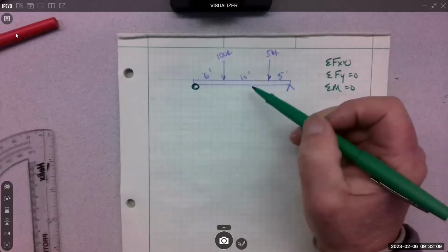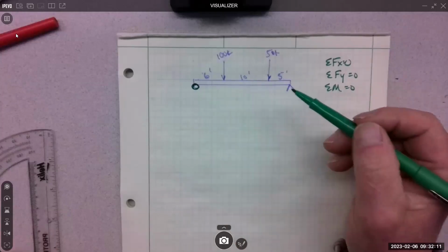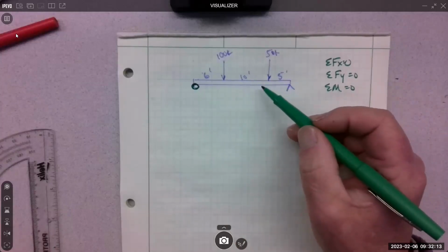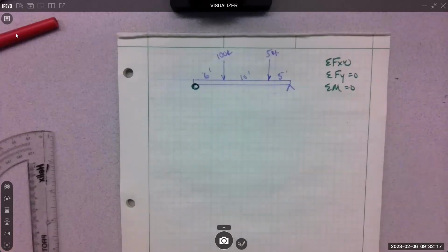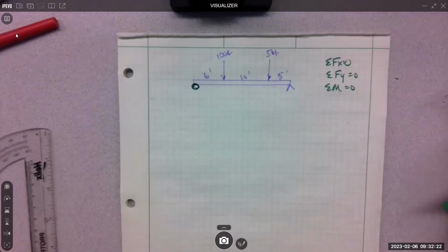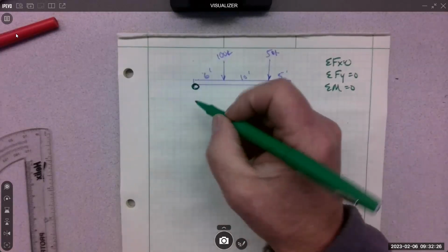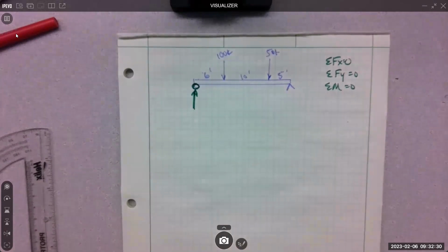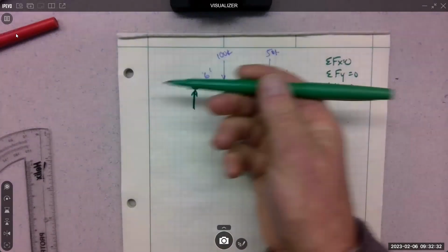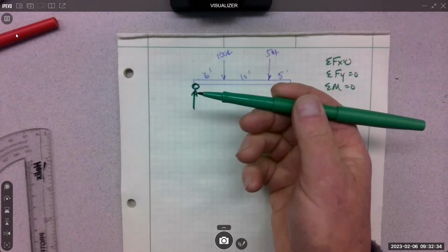When this heats up, it needs to expand, or when it cools down, it's going to want to contract. We want it to do that. We would like bridges to expand and contract so we don't introduce thermal stresses. We do thermal stresses next term in strength of materials, but a roller is just supporting in one direction. It does not support in the X direction.